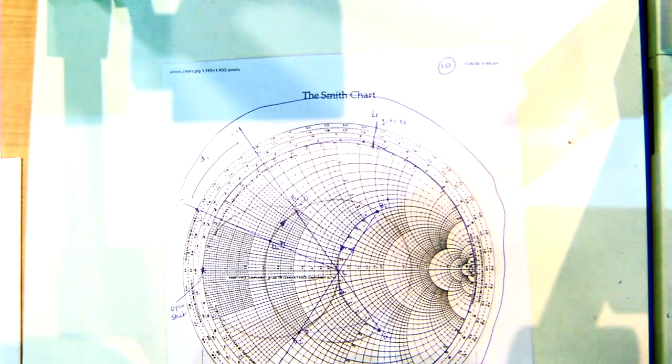Draw the circle with the radius of the impedance. Sure. What does that circle correspond to? All the impedances with the length of the transmission line. So if you connected a transmission line to that impedance, that's all the impedances that you would see at the end, as you were going through the length of transmission line. Good. And it also corresponds to the voltage. When you draw the radius, it also corresponds to the voltage standing wave ratio of that particular system, right?